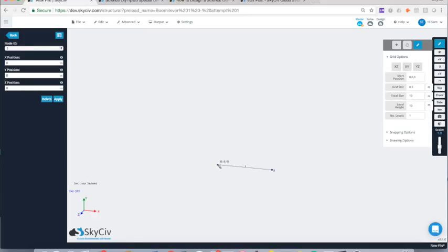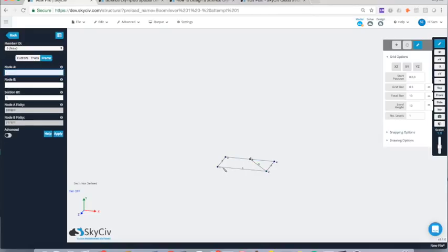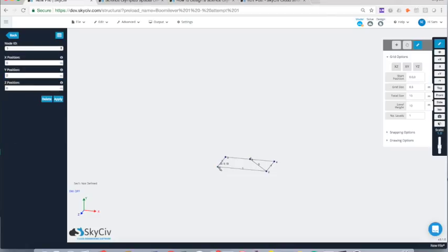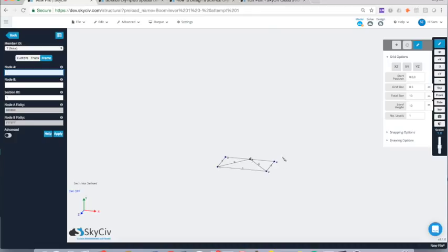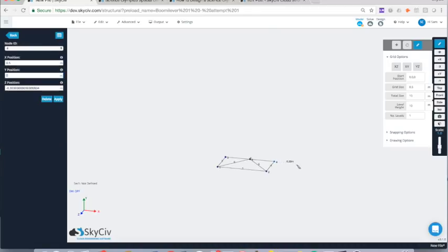And I'm just going to start clicking through to design my model. So I'll probably do something maybe about 30 centimeters wide. And we'll continue across that 0.5 meter span. And you can see it's going to pick up axes that line up with other nodes. And I'll just put a sort of midpoint to midpoint truss structure. It takes a bit of practice to hit the nodes right with the pen tool. And then I'm going to build out a little bit this way as well to make room for where we're going to actually load the structure.